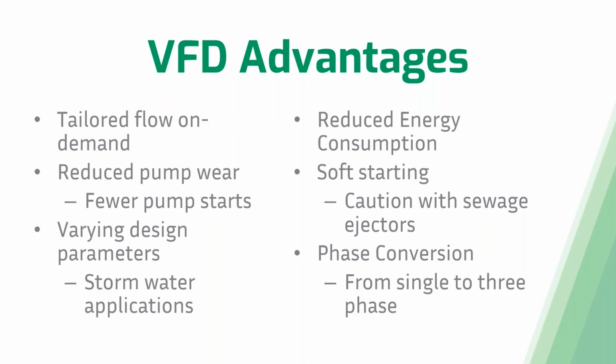And then lastly, you can use VFDs for phase conversion as well, typically from single phase to three phase. This is great when you only have single phase power, but you need the power and capabilities of a three phase pump. So you can use a VFD to convert from single to three phase.